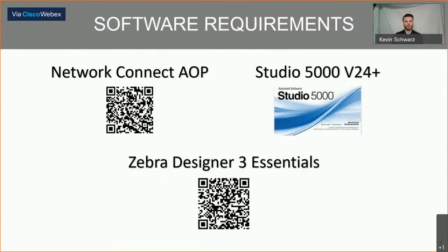For the software requirements, the NetworkConnect AOP actually installs with later versions of Logix. I believe version 30 and up of Logix installs with the AOP already in it. However, if you're running an earlier version of Logix, you can download the NetworkConnect AOP from the link below, which we have in a QR code here. You can scan it with your phone, or in the comments section, we're going to post all of these links that I have coming up here, so you can come back and reference them at any point in time.